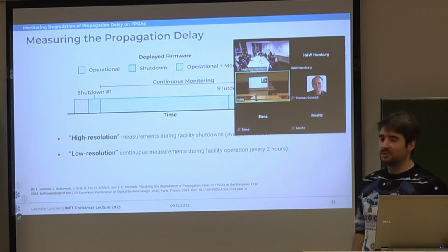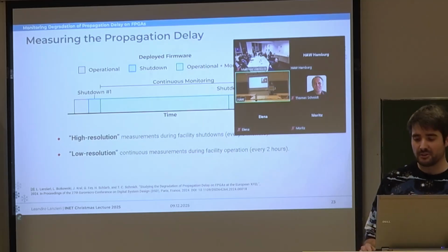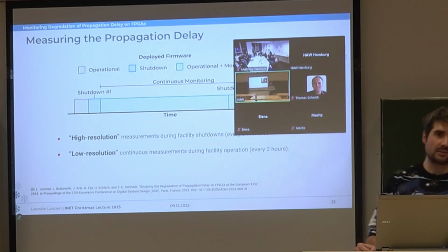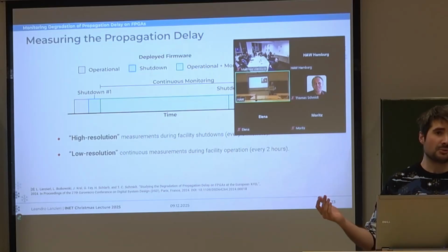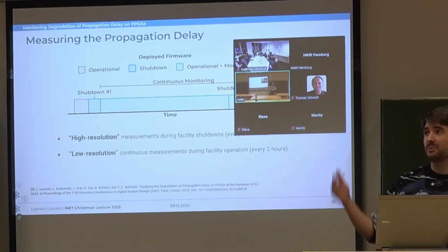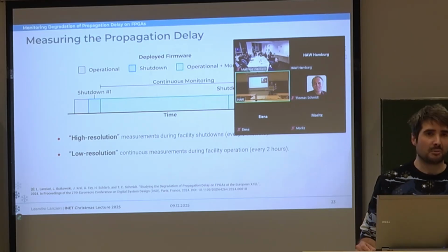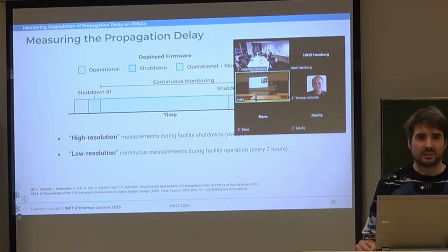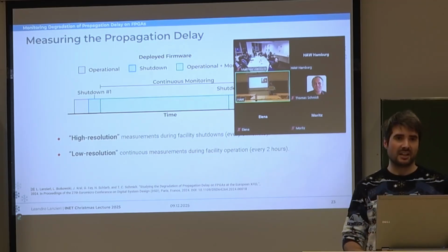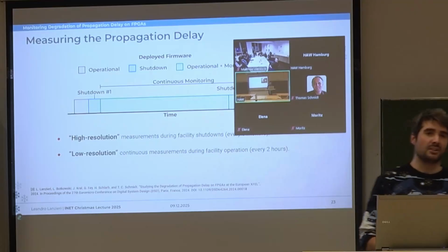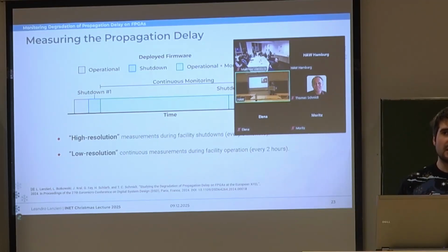No, we didn't look into that, but there are people that did. There are a lot of reliability engineering tests done whenever there's a new node technology. There are papers testing from 180 nanometers until today, covering FinFETs and 3D structures, and how the same aging mechanisms, like NBTI, affect them.